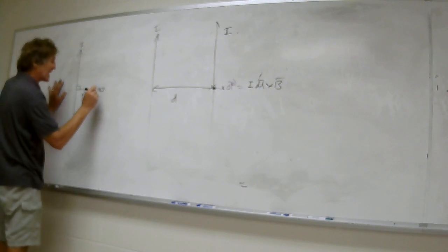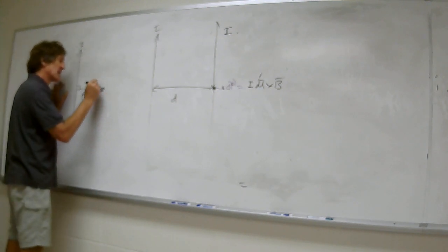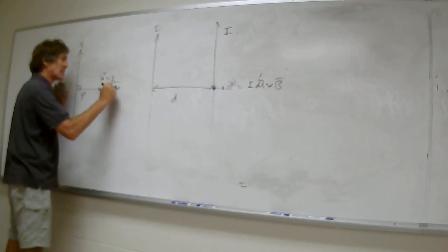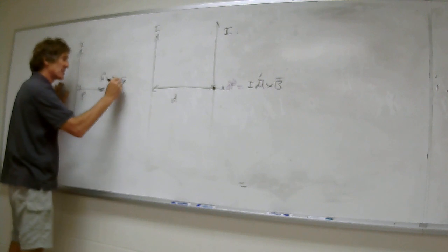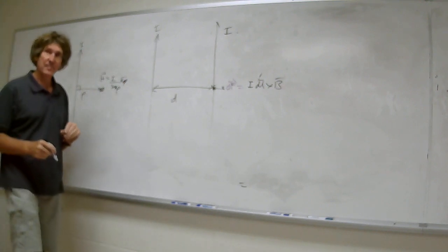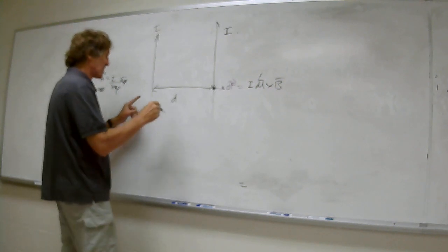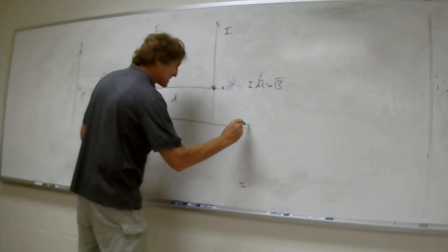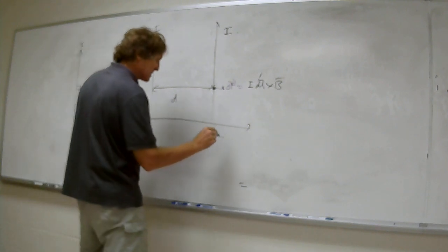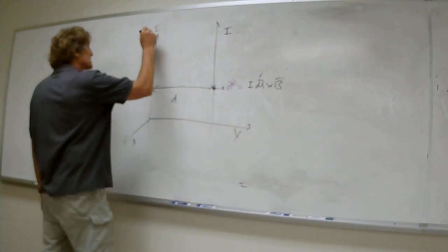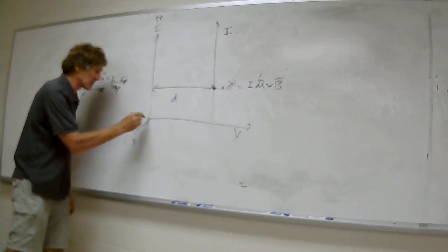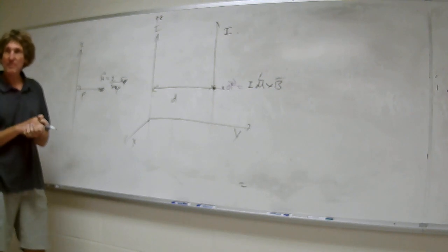Well, first the H field is what? Do you remember? I said it's I over 2 pi rho. I over 2 pi radial distance in the A phi direction, right? Y'all agree with that? Let me give you some coordinates for this one. I'm going to make this the x-axis coming out of the board. This is the y, and this is the z-axis, okay? I'm just giving you some coordinates. Call this the origin. Everybody with me?